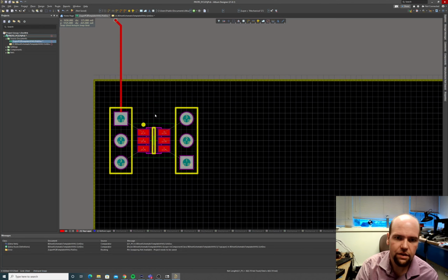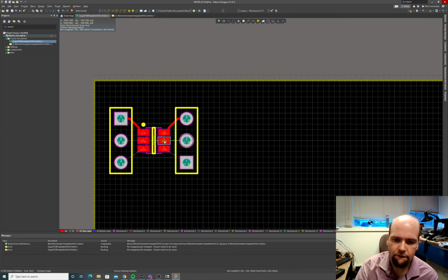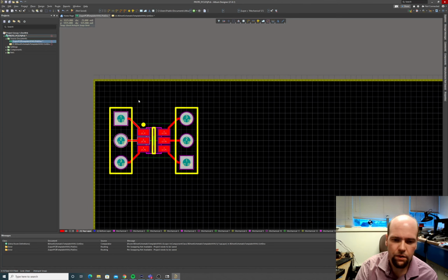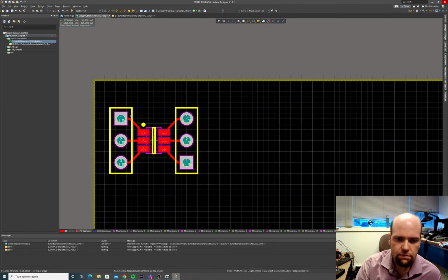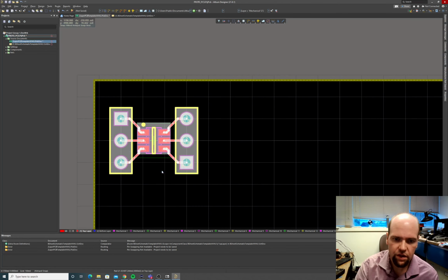Oh boy. My computer lagged here. And the thickness is going to depend on your design. So, normally we might want to do thicker traces than this, depending on what we're looking for. That's fine though. This will work for now. Okay, so for this one, that's good. Make sure our grid is set to 100 millimeters.